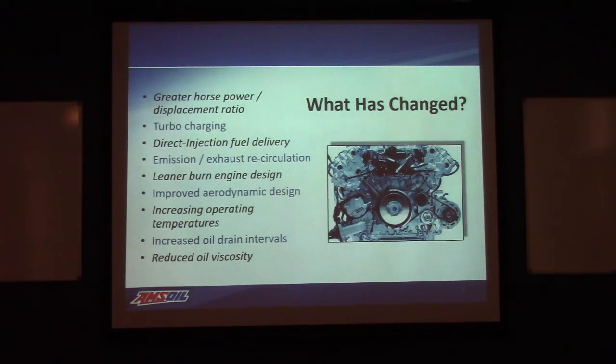And if you look back at what you learned on lubricant fundamentals, you know the rate of deterioration of a product will double for every 10 degrees increase in temperature. So not only are we heating everything up to a higher temperature in the engine, but now our lubricant that is trying to combat these issues is deteriorating at a more rapid rate. So all of these things are causing issues.